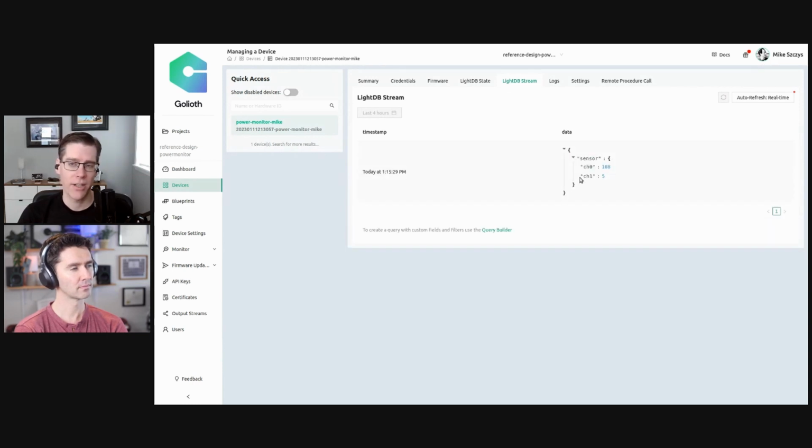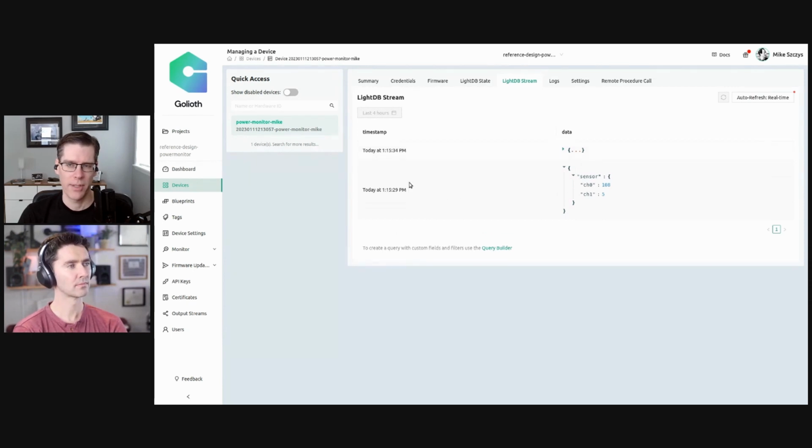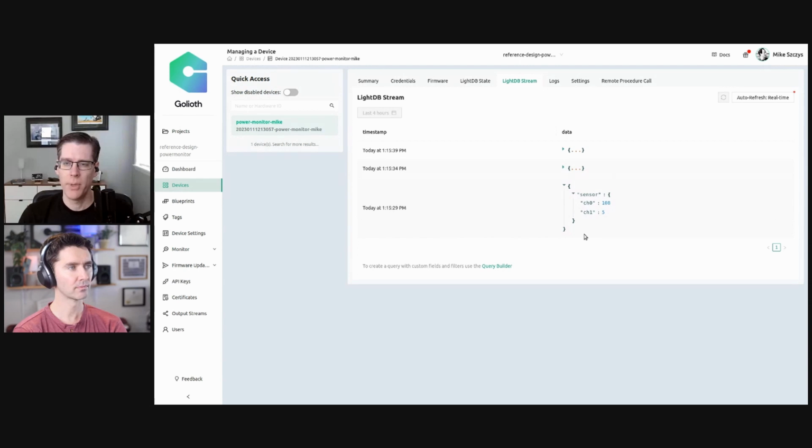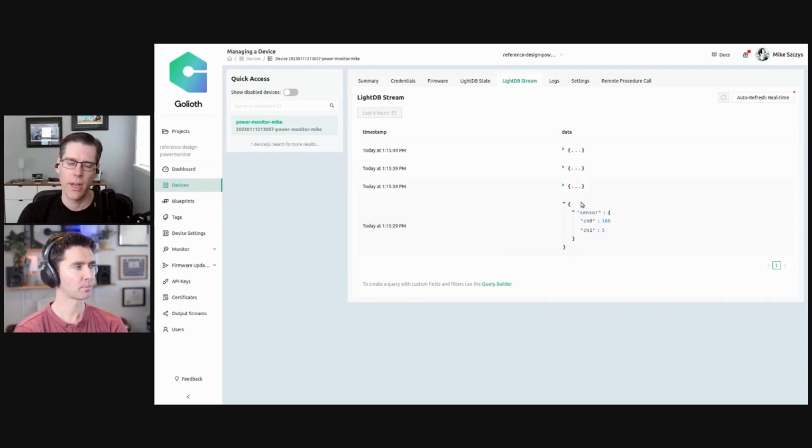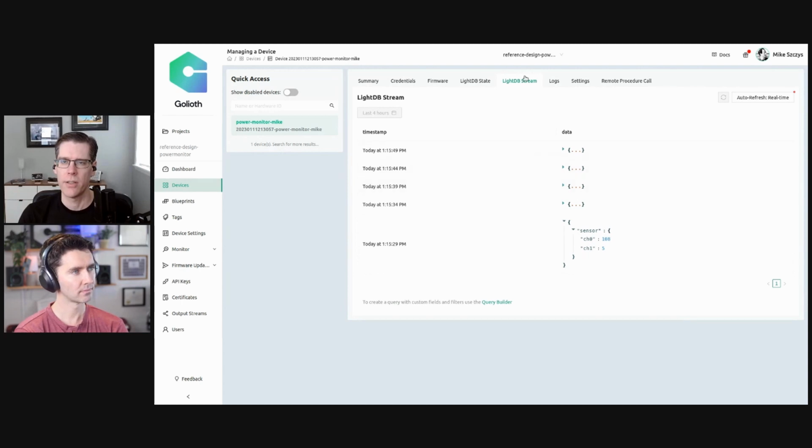It's also possible to cache these readings with your own timestamps and send them in all at once if you're worried about the connectivity being a problem. But you can see I'm just sending raw ADC values, because if you do calculations on the device, it can change based on the machine. I think it's better to get the raw reading and do the calculations in the cloud.